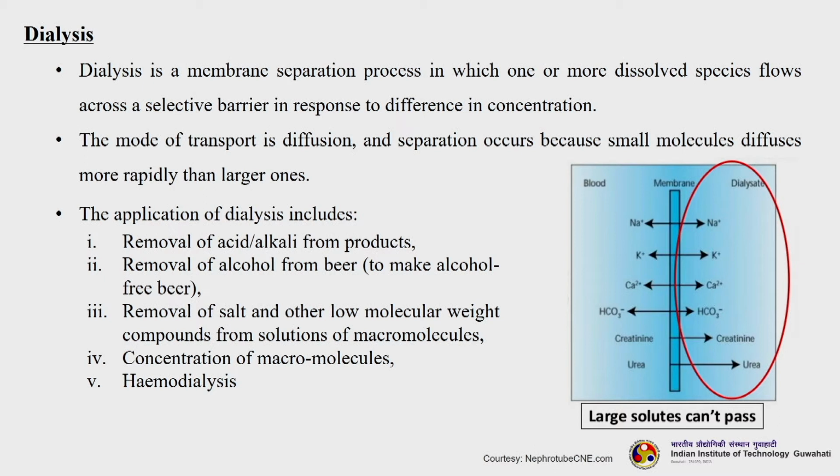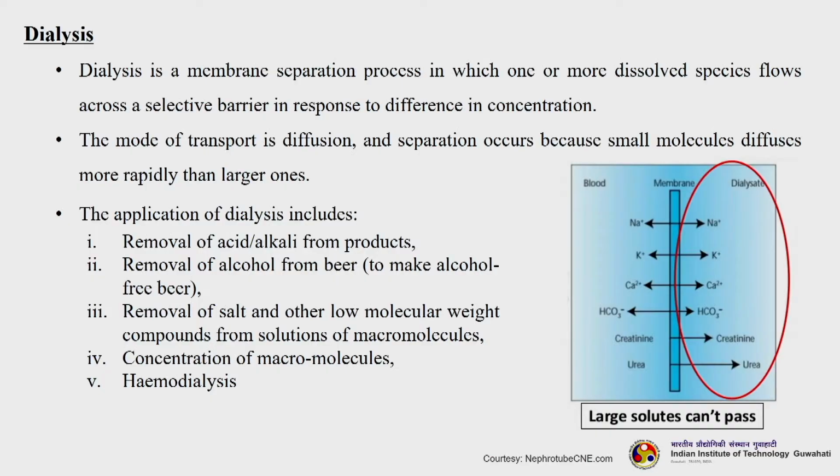The applications of dialysis include the removal of acid and alkali from products, and removal of alcohol from beer. Nowadays, there is a lot of demand for making alcohol free beer in western countries. So, alcohol is removed from the beer using these dialysis membranes. Other applications are removal of salt and other low molecular weight compounds from solutions of macromolecules, concentration of macromolecules, as well as hemodialysis. One of the most prevalent applications of dialysis is hemodialysis.